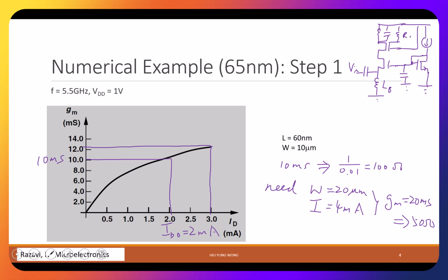And you need to start with some example. I think just use this example. We are also 65 nanometer, right? And the number won't be the same. The point is that you tell me that you extract a certain gm, 80% of the maximum, and then you scale it to give 50 ohm. And again, because it's cascode, this is pretty okay, right? If you are not cascode, there's channel length modulation, and actually you have a lot of channel length modulation because we are using minimum size transistor.